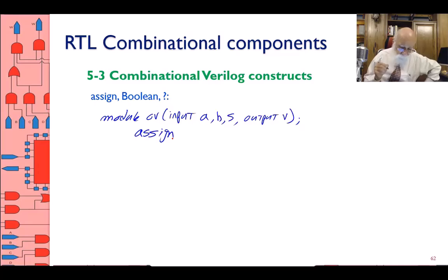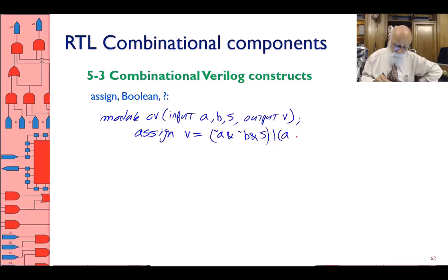Assign V equal tilde A, ANDed with tilde B, ANDed with S, ORed with A, ANDed with B, ANDed with tilde S. That's it.